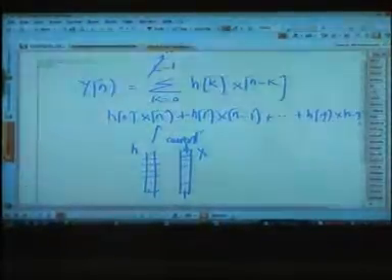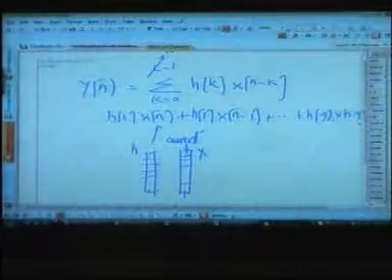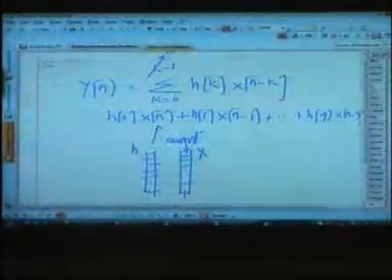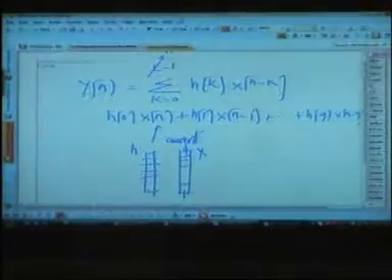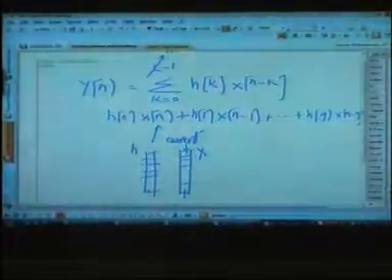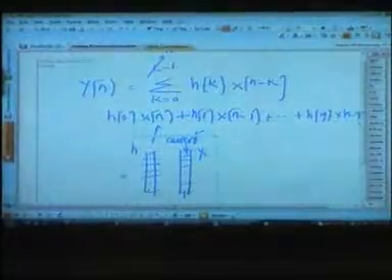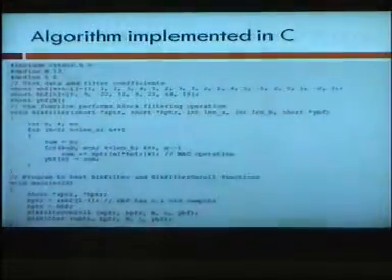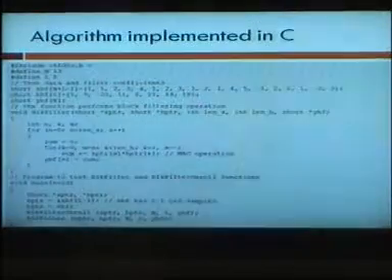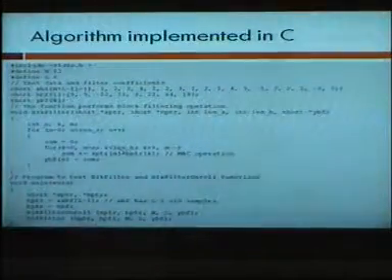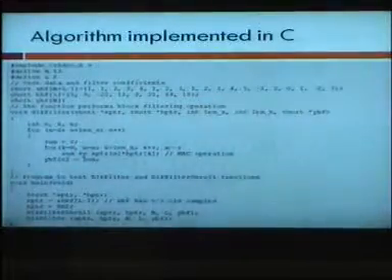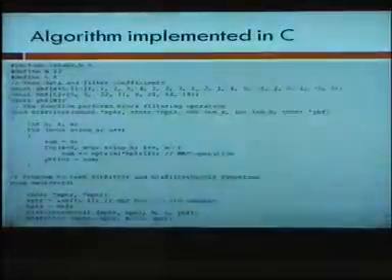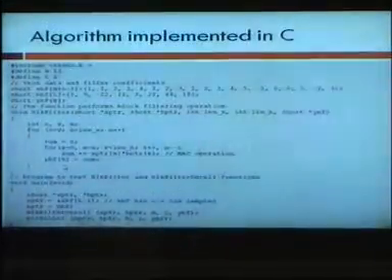So continuously you get data, and you need to maintain this array x. h is a constant, and then in software you take h0 and x0, multiply them together, and add in a temporary variable. Then you take h1 and x1, multiply them together, and add to the previous sum to get a summation. So here the sum is 0 and you run this summation for all the values of h, multiplying and adding into a temporary sum, and once you are done with the 10 values, you put this in your y buffer and go on.